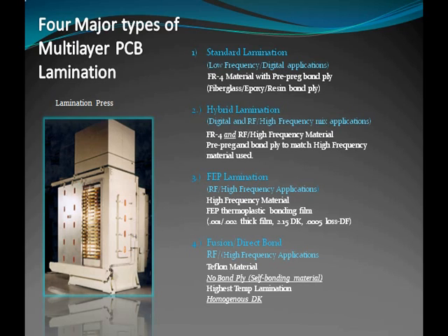Rather, the material is self-bonding when subjected to very high heat and a very lengthy, carefully controlled lamination cycle. Cooling must be equally carefully controlled. Cost is high due to material and labor cost. Transline Technology is one of only an elite few PCB suppliers in the country successfully producing fusion-bonded boards today.